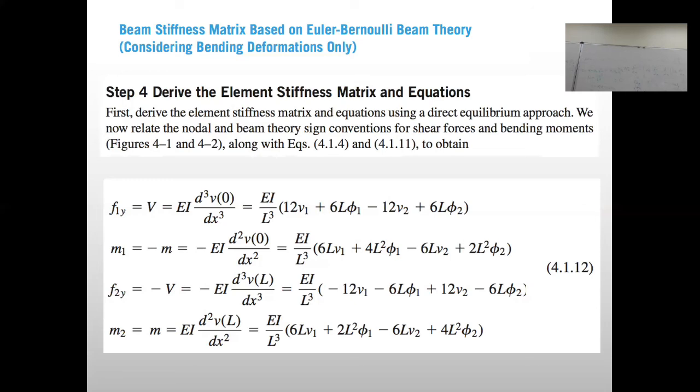Okay, can you tell me the result from here? Just watch. What is the third derivative of N1 with respect to x cubed? 12 EI divided by L cubed. Right? Anything that's multiplied by V1 is this. Okay, you know the third derivative of N2? It's there. Now what do you do after that?